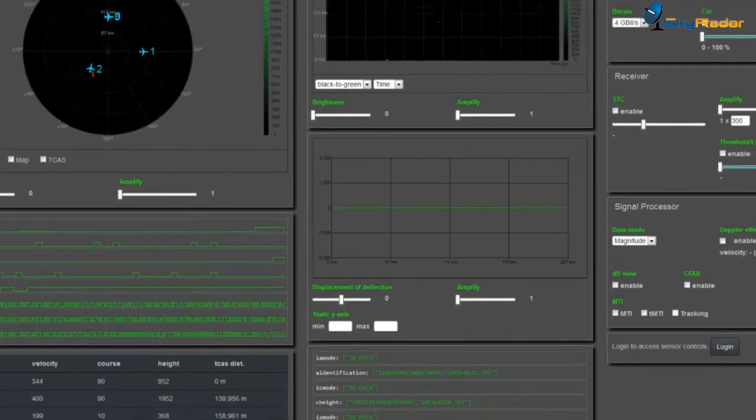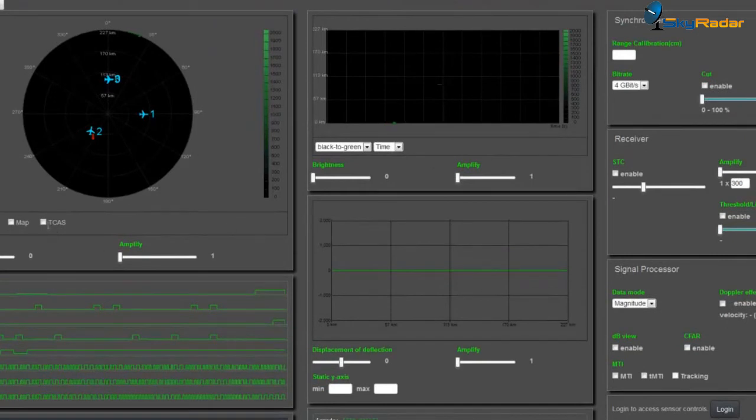Let's have a look at collision avoidance. I switched it on, so the system will now do one circle and will check whether there's any aircraft that is too close to a second one. You see, it has tracked here already an alarm situation, and we have here with the second aircraft the warning that this one is flying below the prescribed height, which is set here as a simple reference figure, 500 meters. You can switch it off again,